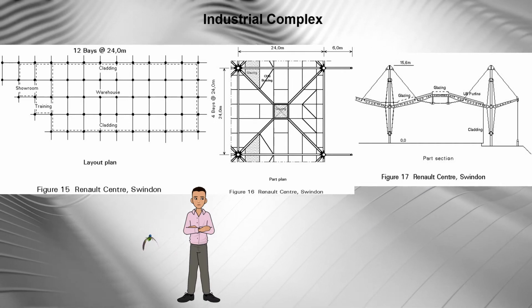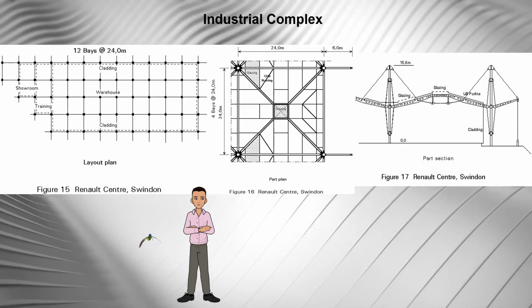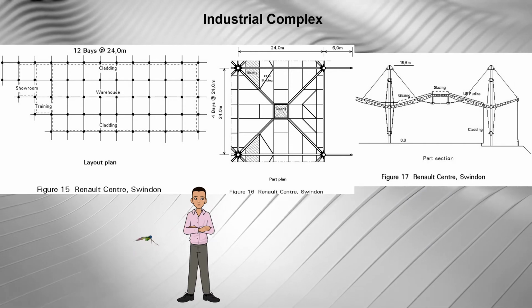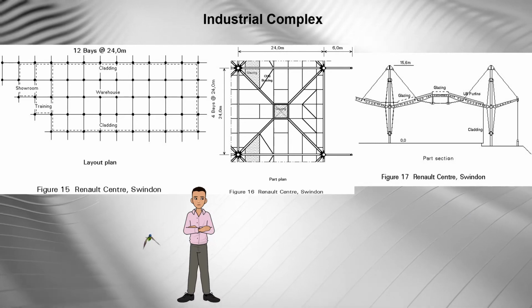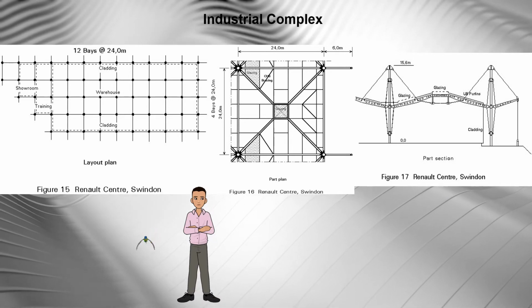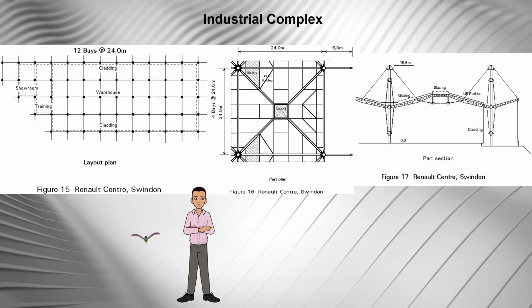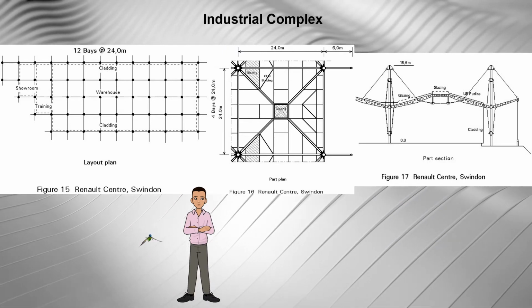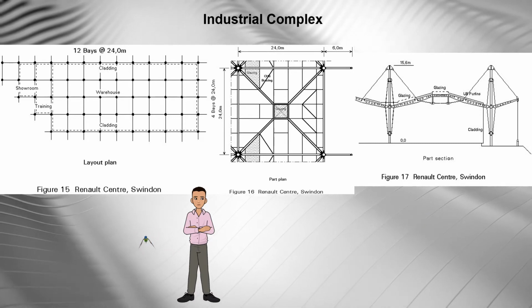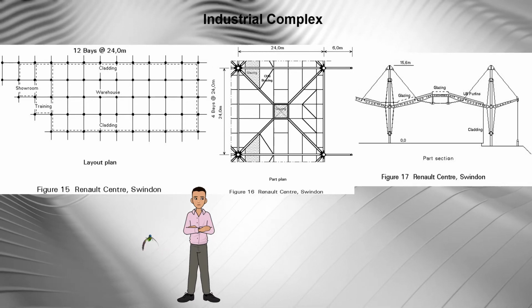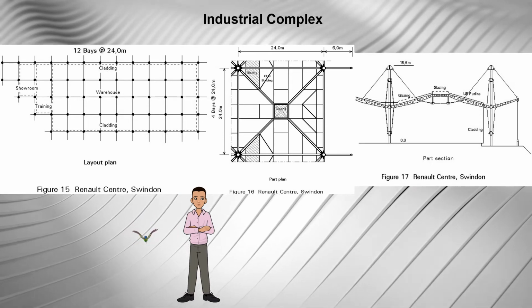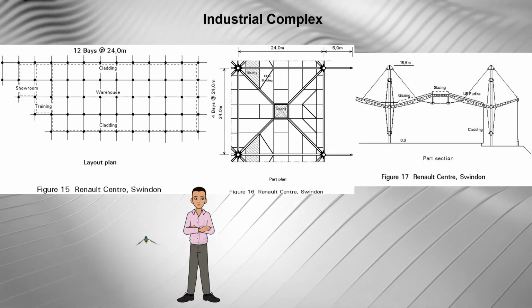The structure consists of skeleton portal frames on both rectangular and diagonal axes. The main verticals are 16 meters high, 457 mm diameter circular hollow sections with rod stiffeners. The roof members are simple trusses formed from shaped I-beams, chambered 1.4 meters, stiffened on the underside with rod bracing and short tubular verticals.